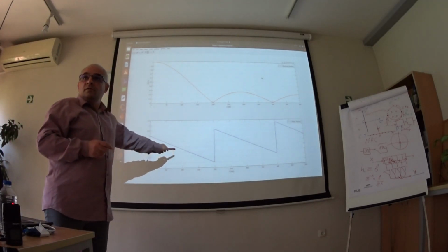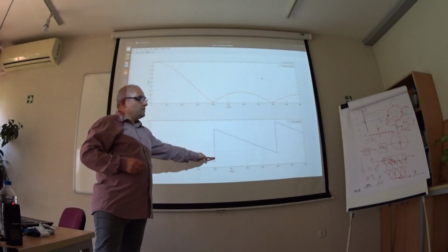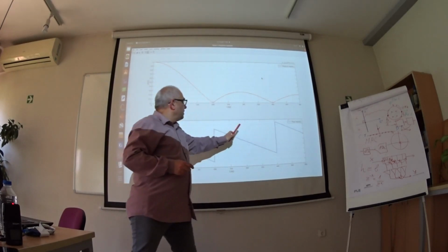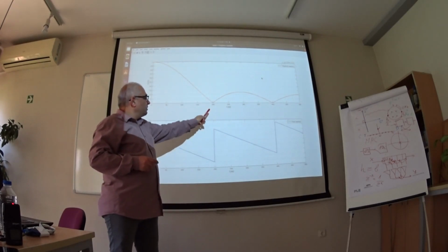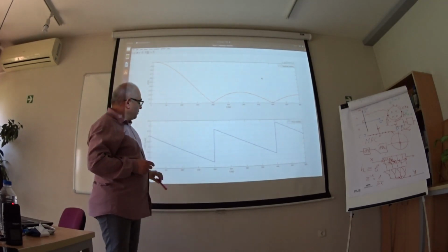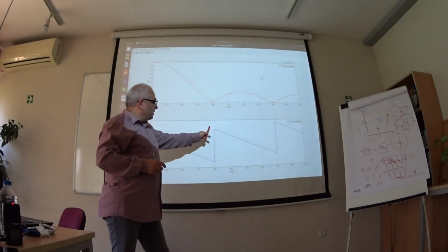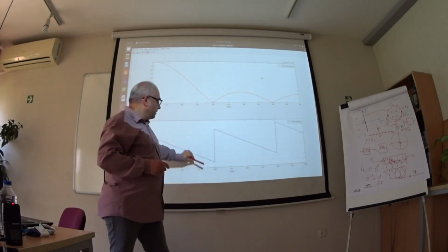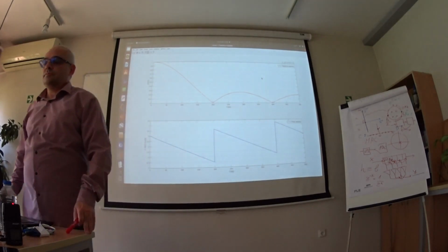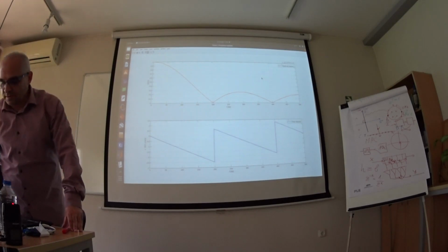It is here. You can see you have discontinuities here and here, but it is not important because here the magnitude response is 0. For us, it is important for the phase response to be linear here, here, and here, and the slope is the same. We do not expect any phase distortion.